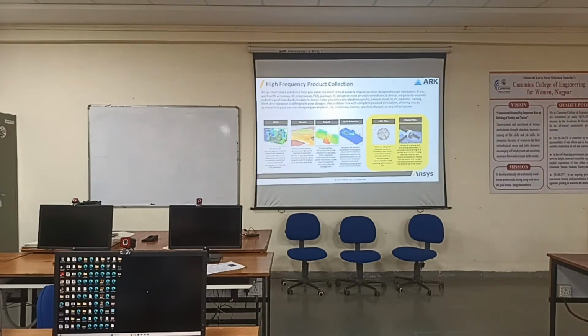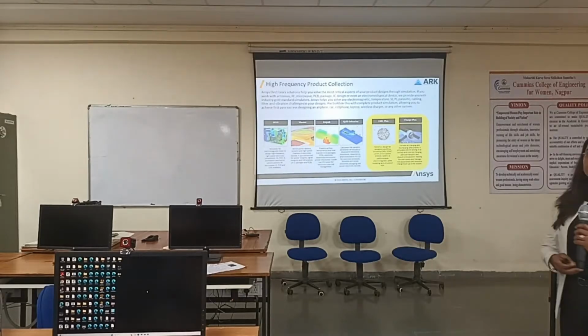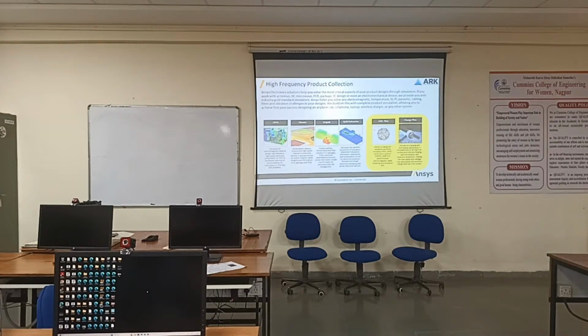So in the high frequency tools, we have HFSS, which we all know. Next one is SIwave. SIwave is mainly dedicated to PCBs. So we already use Arduino boards or Raspberry Pi boards. For the boards available, to find out signal integrity, power integrity, and IR drop analysis, we use this SIwave tool.